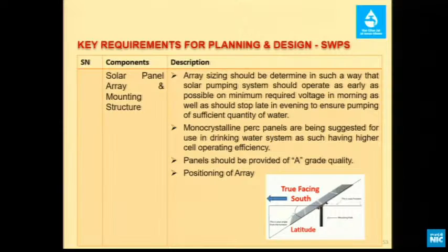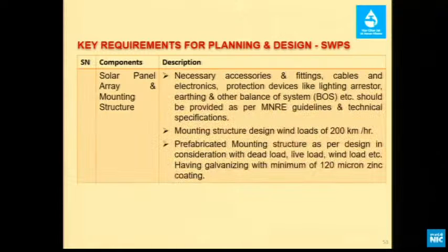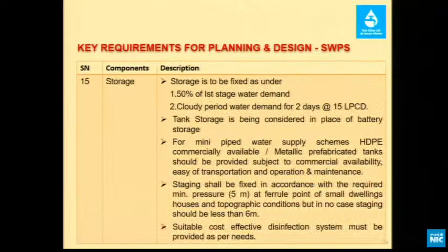And I have depicted a picture of what I was talking about: south-facing panels, and latitude is the minimum requirement. And we should ensure that the quality of my panels is A grade. It should be of the quality of next. Simply, only one thing I am asking: as defined in the MNRE guidelines, the structural zinc coating shall be 120 micron, not 80.